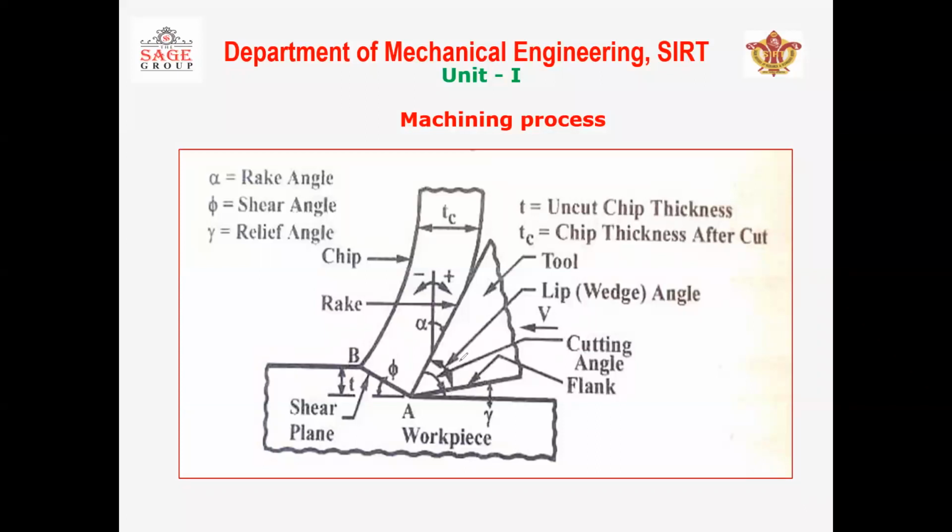Yes. So let us define one by one. What is a rake angle? What is shear angle? What is relief angle? t is the untouched chip thickness. Untouched chip thickness means this is the untouched chip thickness. t is the chip thickness after cut.